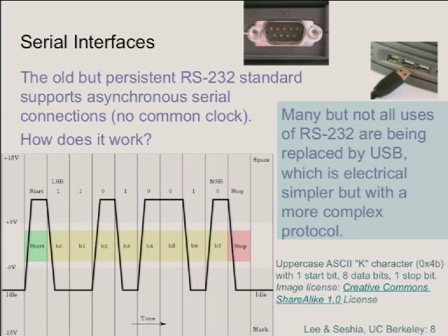RS-232 is something you typically see on a device with a connector like this. This is one of these DB9 connectors. For the most part, there are really only 2 of these pins that you care about: the send data and the receive data, and then a ground line, a third one. But there's a bunch of other stuff that teletypes needed, and therefore it's there.